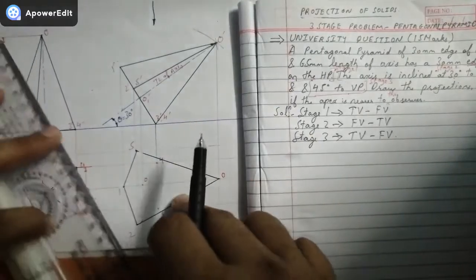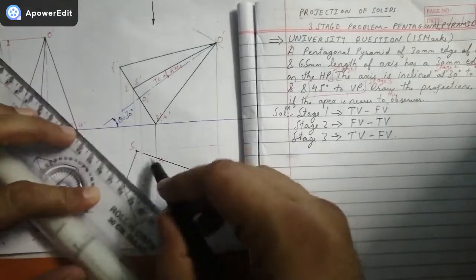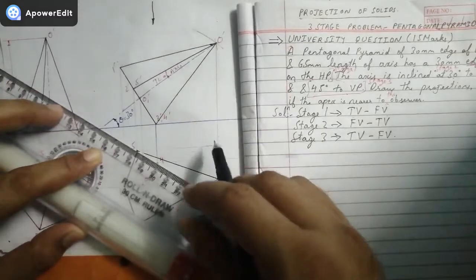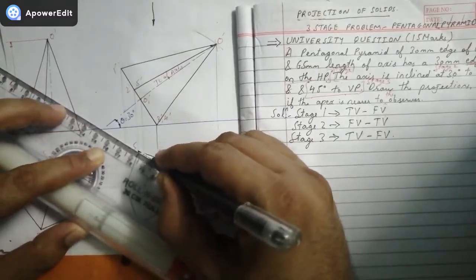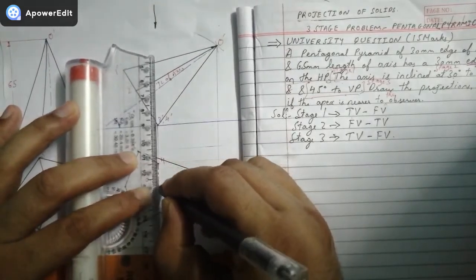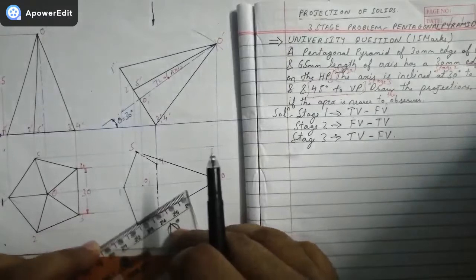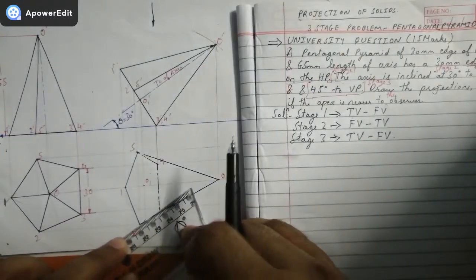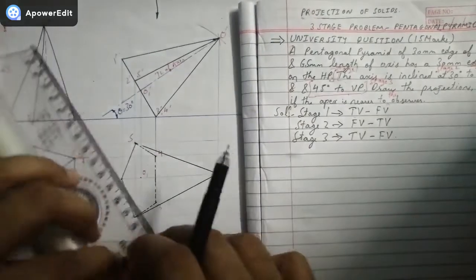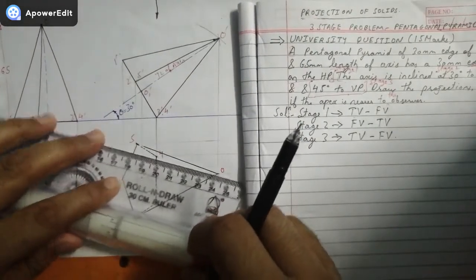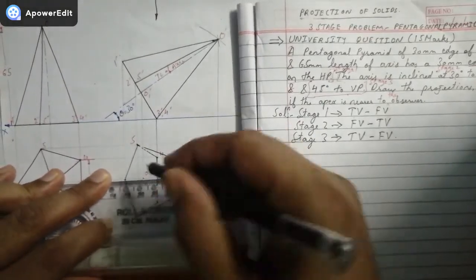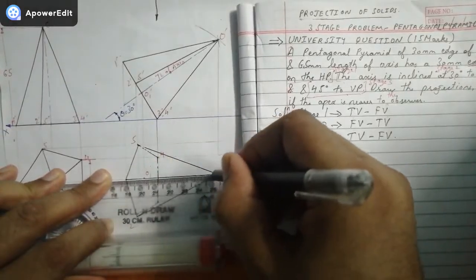So let us draw the base edges first. Now the left out base edges, that is 5 to 4, 4 to 3, 3 to 2. Any guesses? These would be definitely the unseen edges, that is the hidden edges, because these are coming on the other side. Okay, so one by one we have drawn the hidden lines, that is the hidden base edges. Okay, so as we are done, you all can see this, and even now O24, O23 and O21 edges are left out.